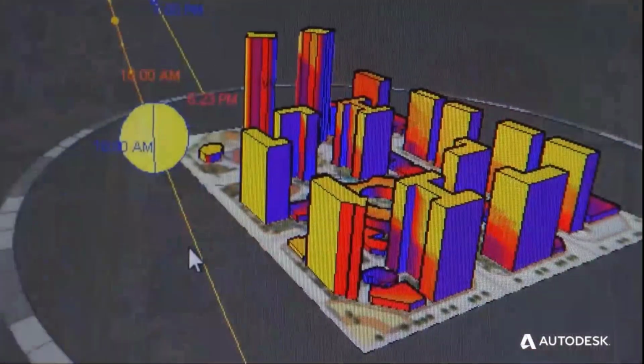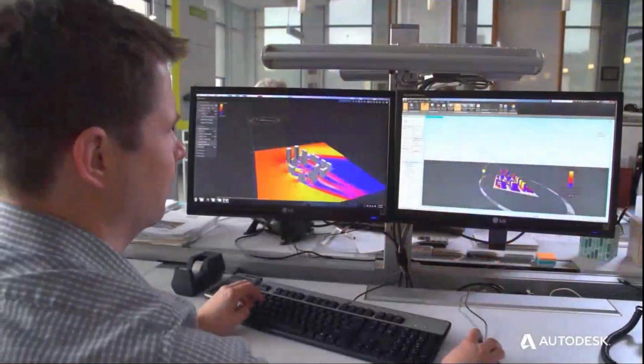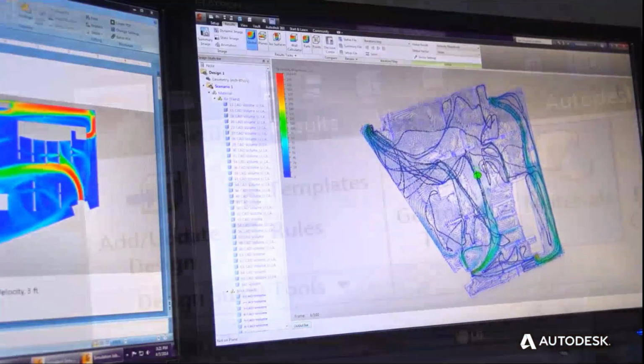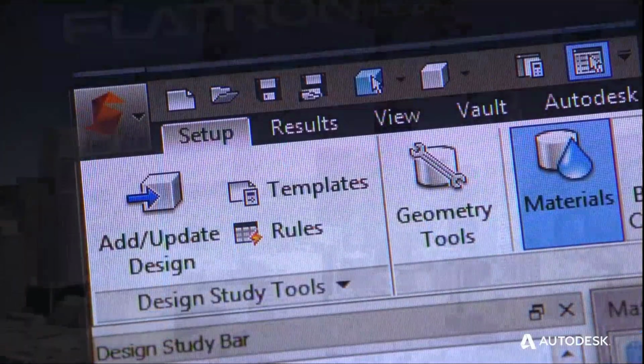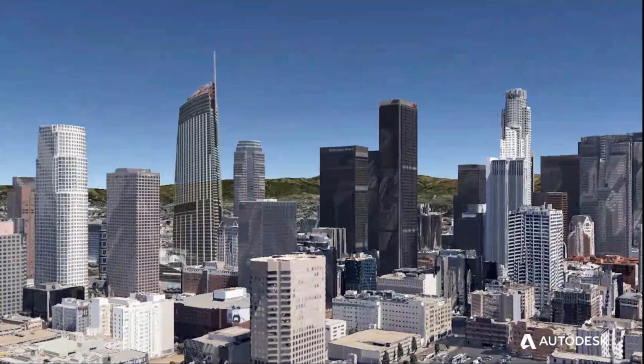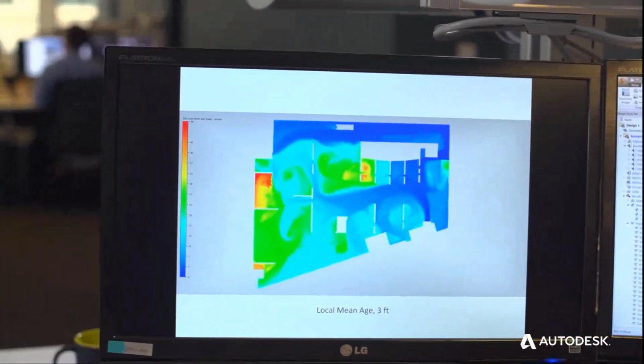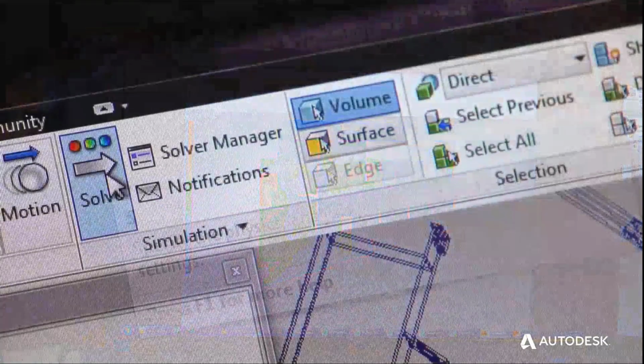Then once we got a little bit deeper, we'd start moving into the other Autodesk building performance analysis tools. That would allow us to refine the energy analysis and do more detail on the big picture system options. What Autodesk Simulation CFD would allow us to do is look at how those systems are operating in terms of the airflow in the space and the comfort. We've used Autodesk Simulation CFD to evaluate the parking garage at Wilshire Grand so that we can design the fan systems to operate more appropriately to the specific end-use need so that we have a safe environment.